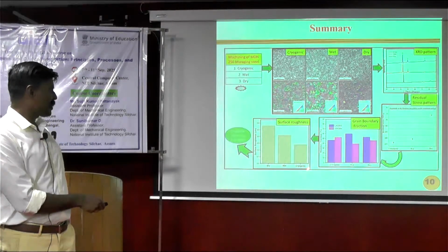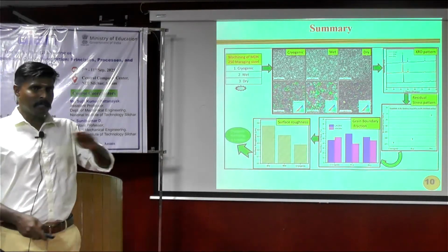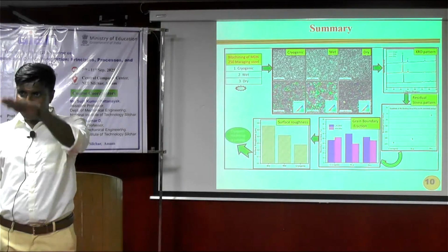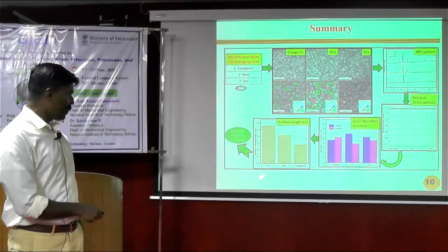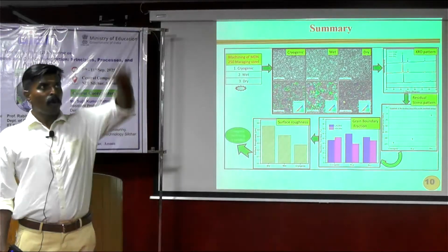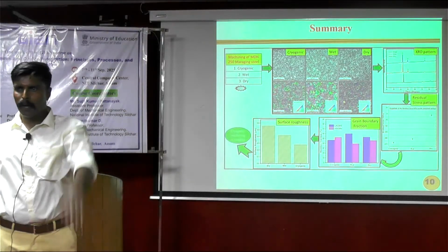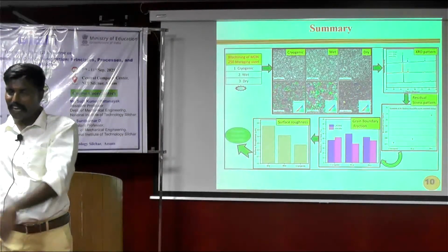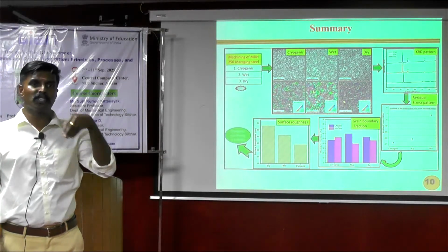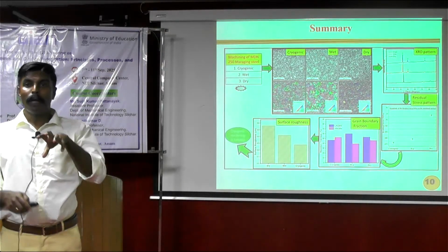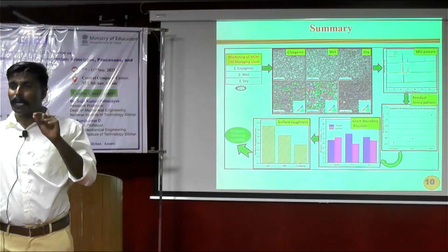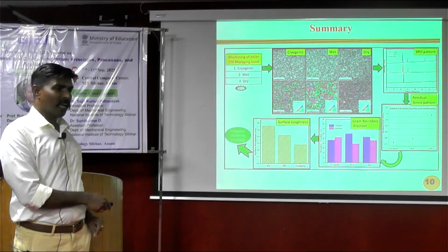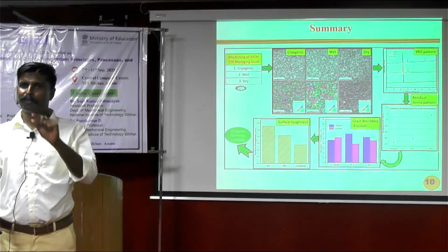From that we understand that the cryogenic condition has the minimum surface roughness. Minimum surface roughness means the waviness in the surface is less. In the case of the dry condition, without any cutting fluid, the waviness is large, going up and down, up and down. So this kind of oscillation is there, and from there cracks will start and failure will come. A perfect surface finish means surface roughness should be minimum. Out of the three conditions, the cryogenic condition gave very minimum surface roughness.